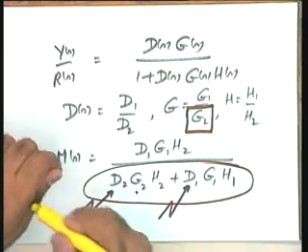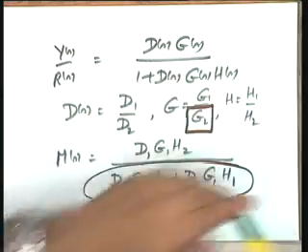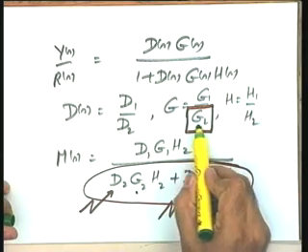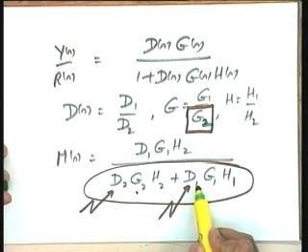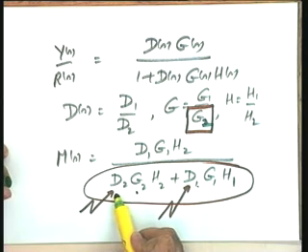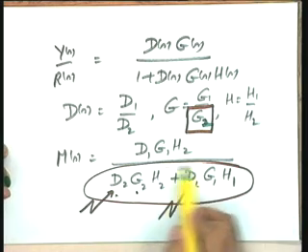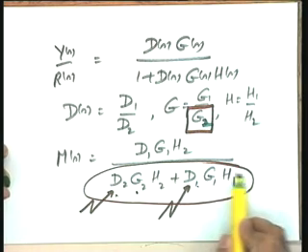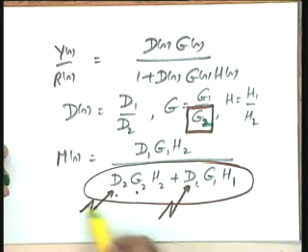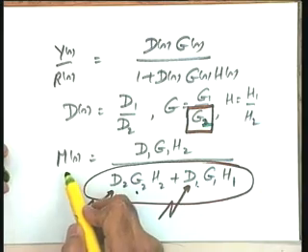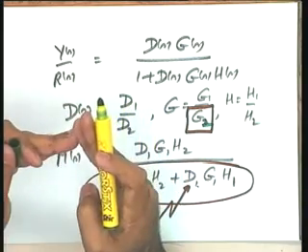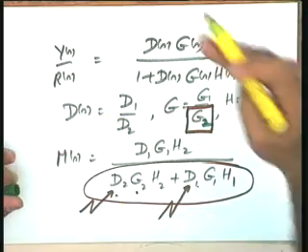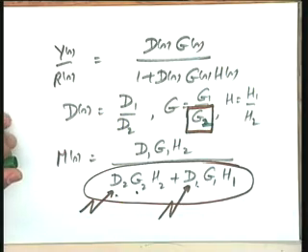So through feedback action, I just want to say this point. You see that in the open loop case, the response G2 was not acceptable to you, but through feedback action you can appropriately choose D1 and D2, so that the roots of this particular polynomial, which will become the poles of the transfer function M(s), can be suitably placed in the S plane, and hence the dynamic shape of the response can be suitably given.